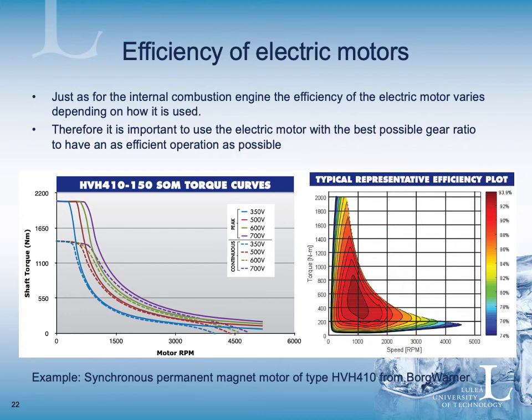If you continuously have a high torque, meaning a high power, you need to cool away a lot of energy. But for an electric motor, normally it is not an issue to have a torque peak for a few seconds. So you can have a smaller engine that you overload for a short duration of time without getting into problems.